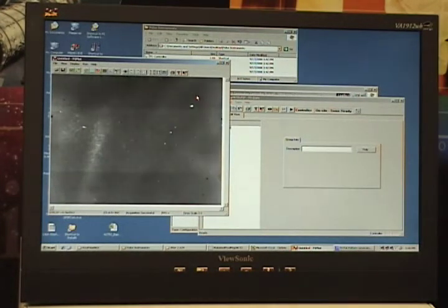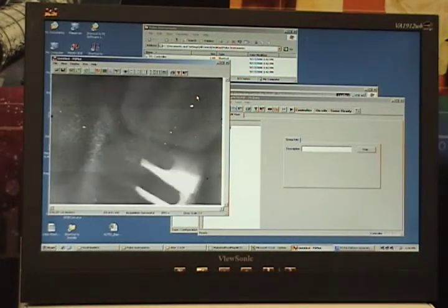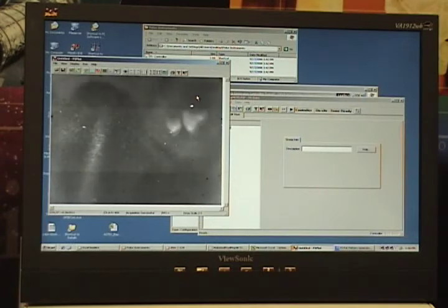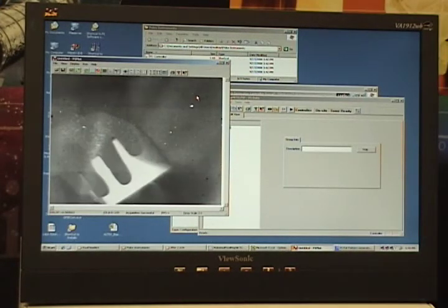In addition to the 1,000 frames of live video, we also have 32 frames of the device looking at a hot reference and 32 frames of a cold reference. We could use these to calculate sensor performance and also to build image correction tables. First, we will count bad pixels.